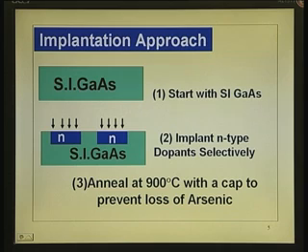So, if you implant for 10 seconds, I into T gives you the total charge, divided by Q gives you the number of atoms that you have implanted. The atoms come in the form of ions, but when it comes and implants on the wafer, the path for the beam is in that direction, ionized path, but it is neutralized. It does not remain as positively charged, it is neutralized by electrons coming from the back door.